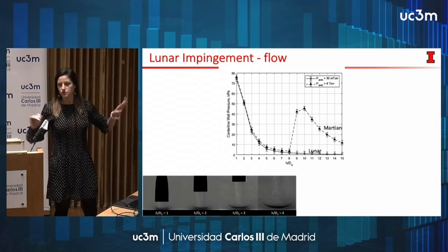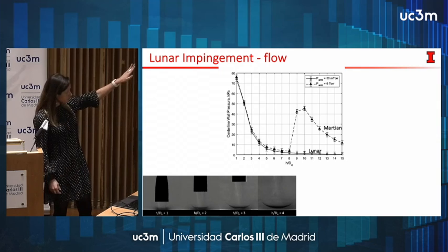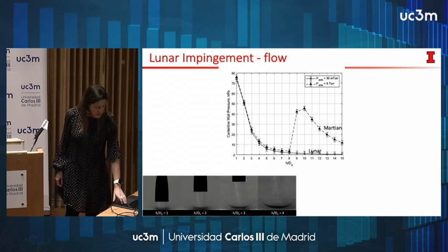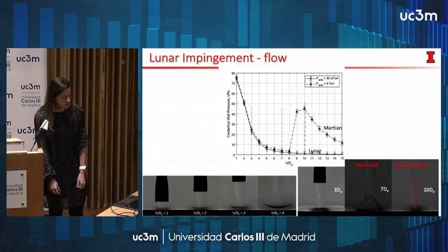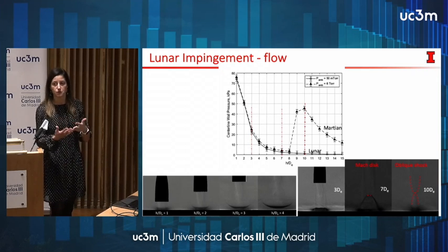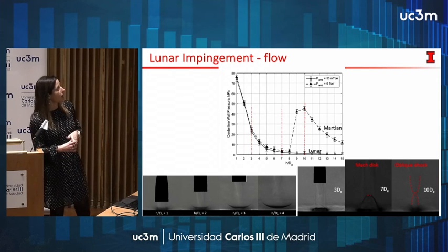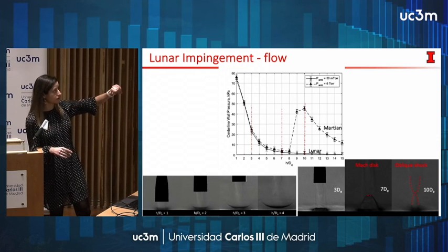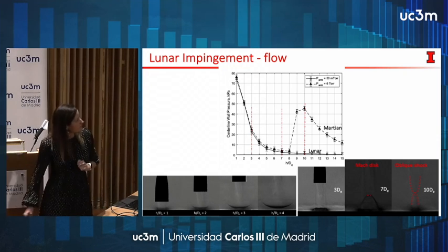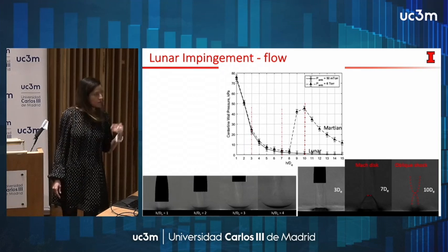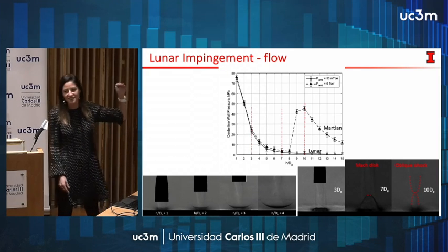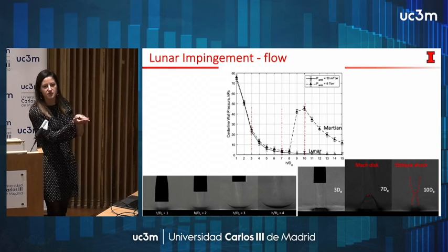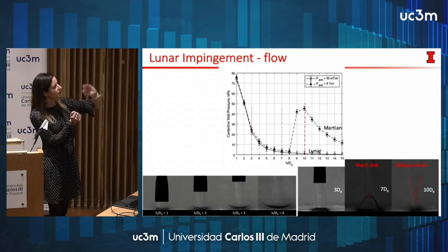You just have a curved choke and radial jet, but it's the same. It doesn't change it. If you do this for the Martian case, you actually can find 3 types of flow configurations. Up to 4 non-dimensional nozzle distances, you have a surface shock. This is totally dark. But if you believe me, in the image of the middle, you see a Mach disk that changes the distance to the surface as you vary from 4 to 8 diameters.